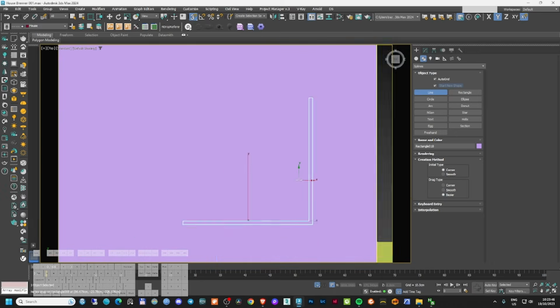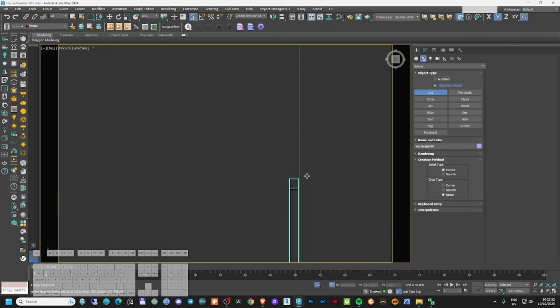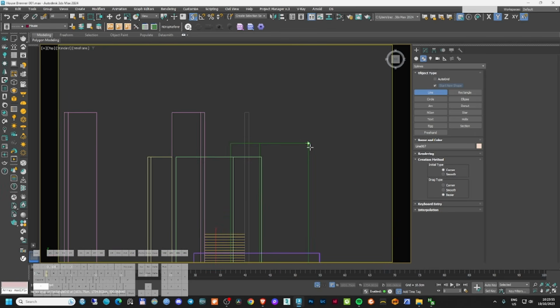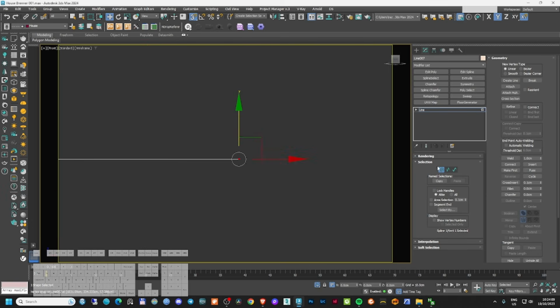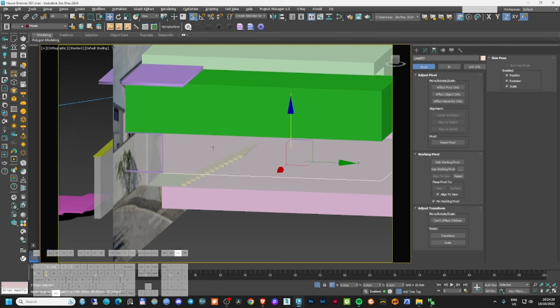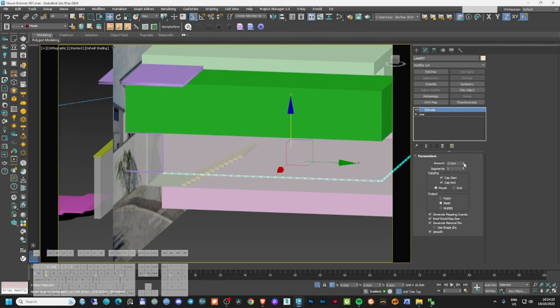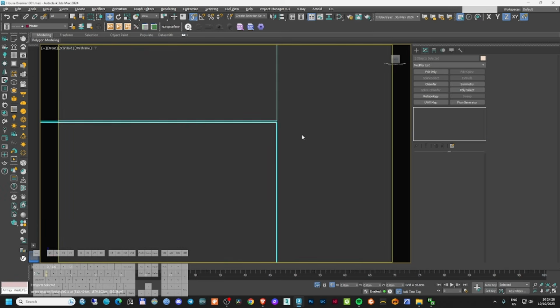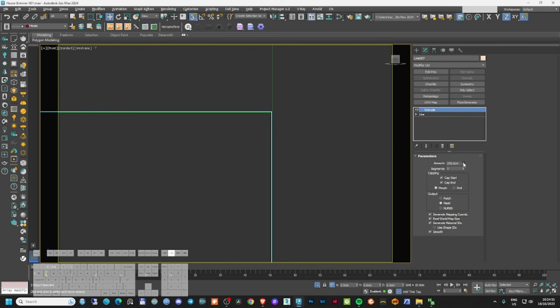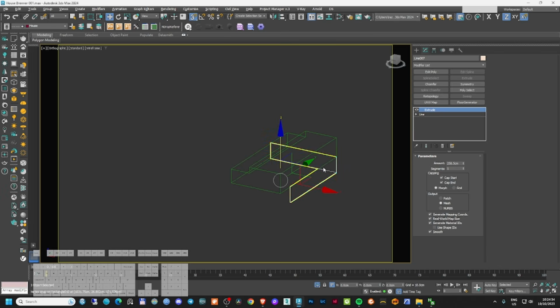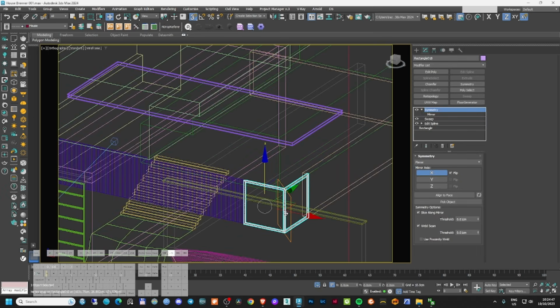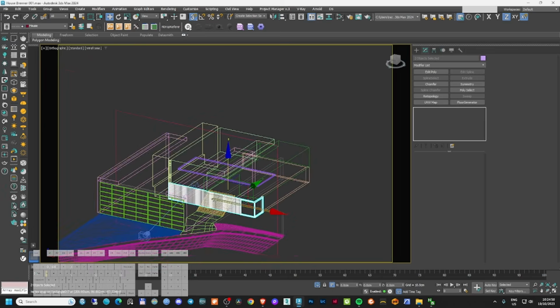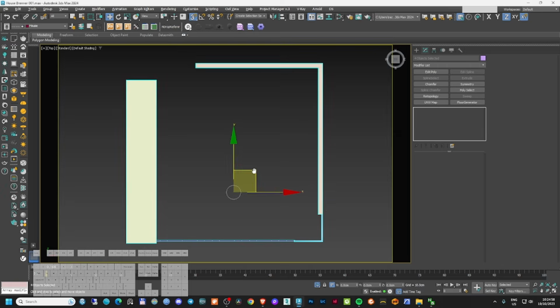Yeah, for the rest we're just going to create here a wall behind, so we know for sure that everything is going to be closed. We'll apply an extrude to this. Yeah, this wall is just to not get strange things behind. And I will apply also a shell. This shell can go 35 centimeters, and then I will select all of this and create a floor.